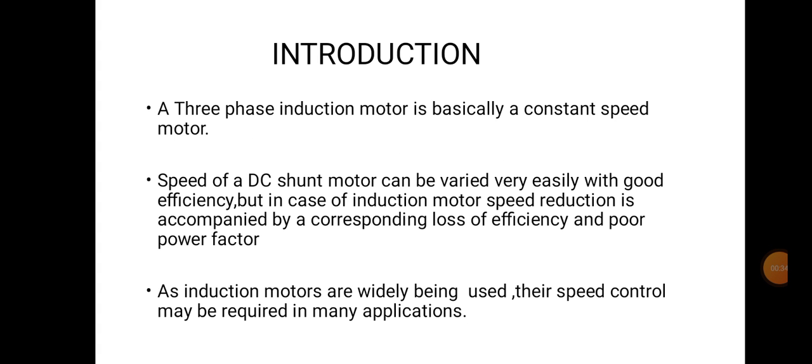And its introduction. A three-phase induction motor is basically a constant speed motor. Speed of a DC motor can be varied very easily, but in an induction motor, speed reduction is accompanied by a corresponding loss of efficiency and power factor. As induction motors are widely used, their speed control may be required in many applications, such as car, bike, etc.